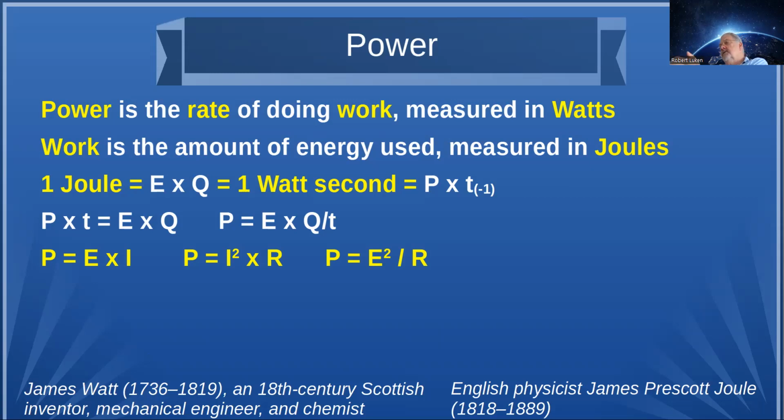In other words, your source has to match the load for maximum power transfer. The load being the antenna and all the gubbins that goes with it. You normally connect that with what we call a feed line. Typically, it's going to be coax. It could be ladder line or twin lead.